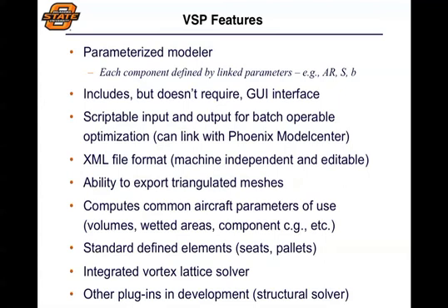Those airfoils are already predefined. You can pull those out. It also computes a lot of the common aircraft parameters that we need to use for analysis, such as the entire surface area of the vehicle, which is important to calculate drag, the planform area, which is important to calculate lift. So it allows you to calculate these directly in VSP as part of the definition. It gets us defined how we typically use those in aircraft design.